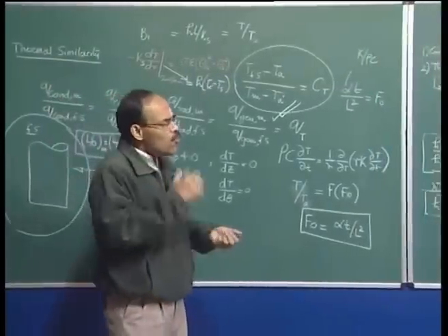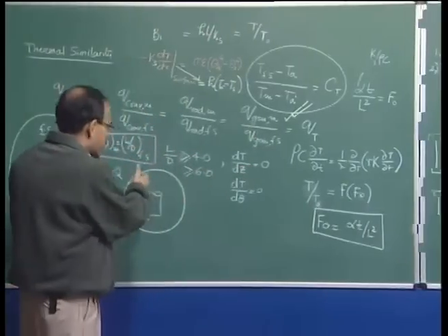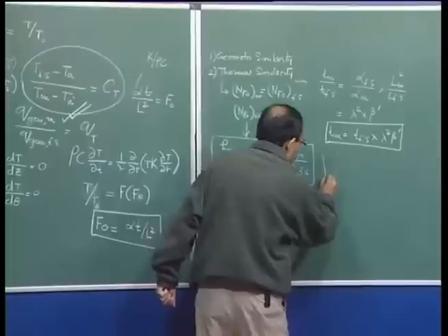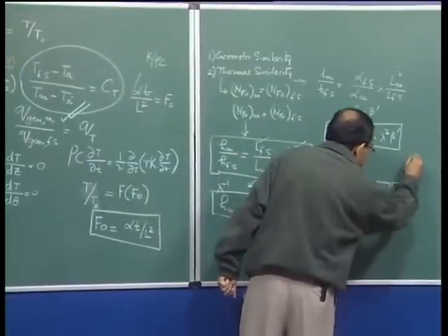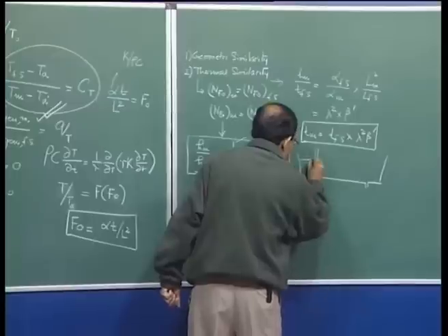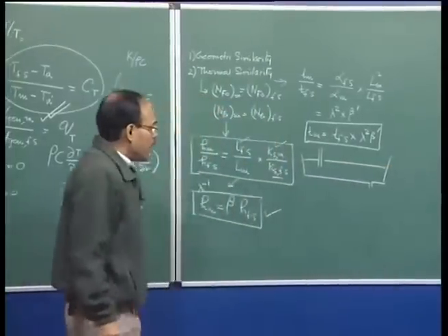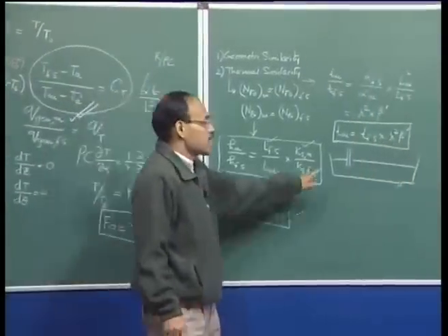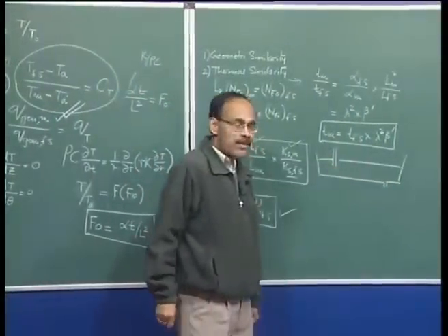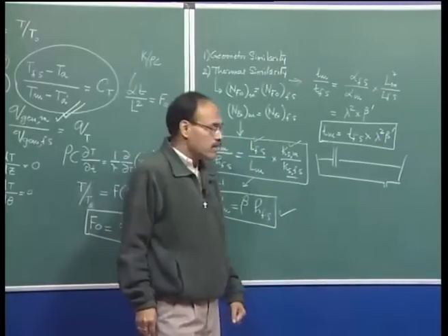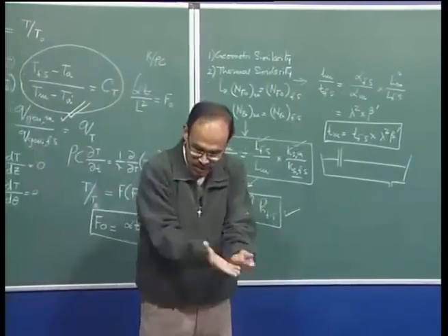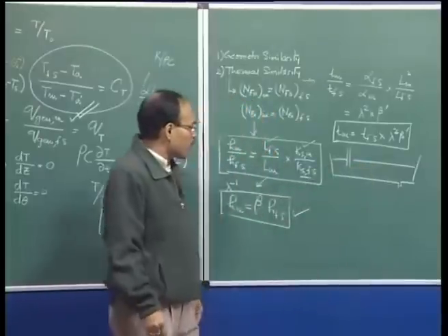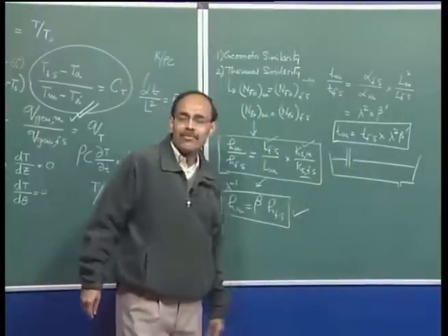Now, take a practical case, though this is a very simplified scenario. Take heat flow in a tundish, for example, a single strand tundish, which I am showing very simply, and I want to carry out a laboratory scale model. I have chosen a scale factor. I want to do the experiment with water, for example, and suppose I have made a glass vessel, tundish shaped, and I wish to carry out the experiment. I want to see the flow pattern also, but I want to consider non-isothermal flow.